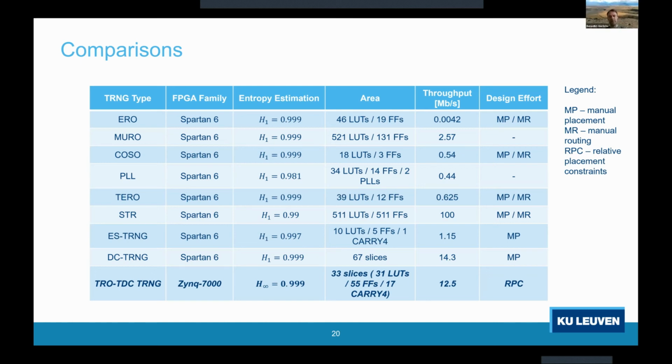The number that I'm looking for is how much time passes before the first bits become available. There's some kind of setup time. These throughput numbers express the throughput once everything is up and running, right? But initially the TRNG needs to accumulate some entropy when you power it on; it's not going to spit out bits immediately. But this accumulation time is the same between every random bit that you output.